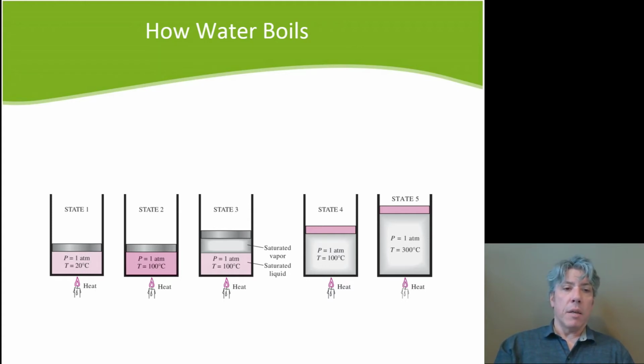If you take water to a high elevation where the boiling temperature is lower, the reason the boiling temperature is lower is because the pressure is lower at that area. If you increase the pressure, let's say you have a piston cylinder device like this, and you increase the pressure on the water, well, you will increase the boiling temperature. So the boiling temperature and pressure go hand in hand, and they're called the saturation temperature and pressure. And therefore, state 2, 3, and 4 are all three referred to as saturated states.